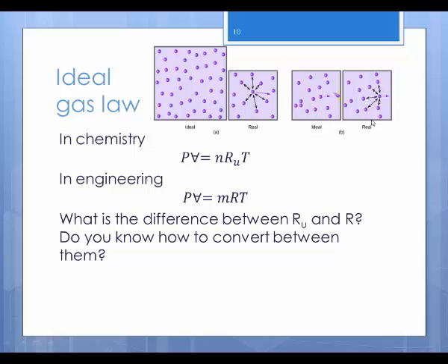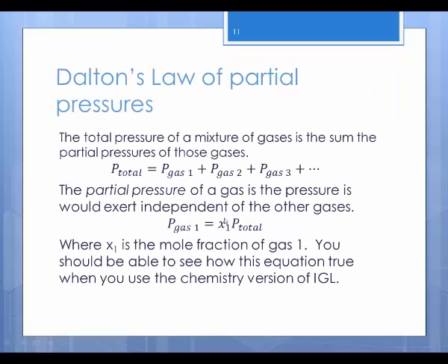So if you know it's an ideal gas, it follows these two basic assumptions, then that indicates that you can use the ideal gas law, which means that if you use this form where you convert this to M over V density, then you can find the density of your fluid gas, and you now have a fluid property determined for a fluid problem from a law that really came from chemistry, and that's really valuable.